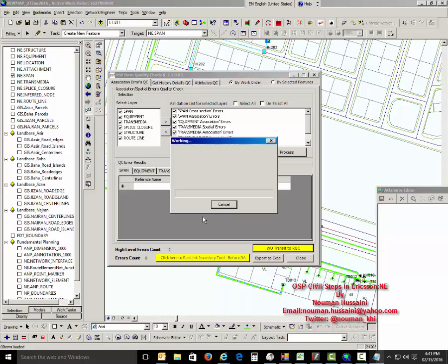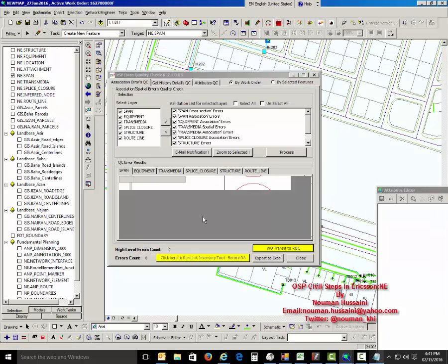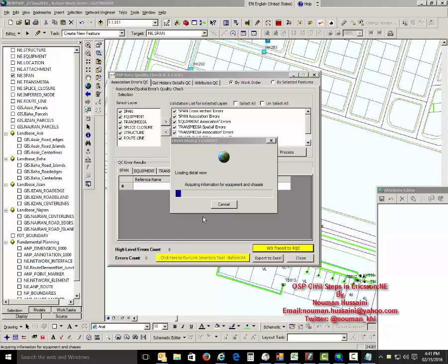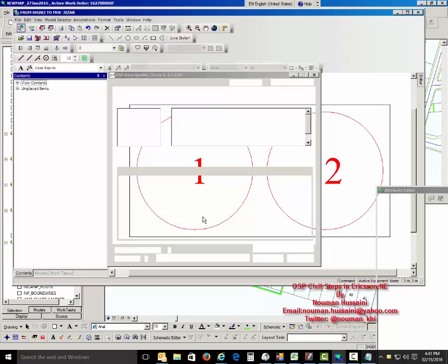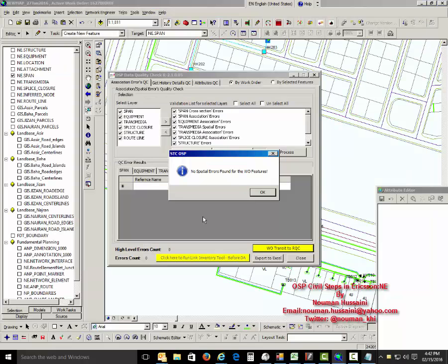Then from the models tab in the table of contents, select the span, correct model, whatever you want, and then locate the existing handhole or manhole, and from that structure vertex draw your span to a desired length as told by your manager or project manager or design QC engineer, and place this. Finish sketch by F2, then place.